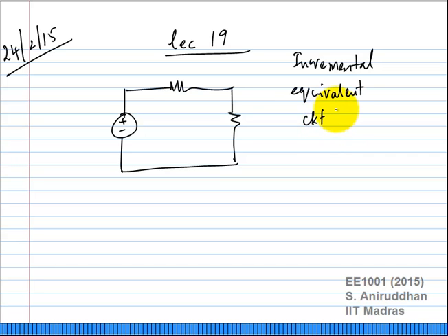What happens to the voltage source? The value of the voltage source is delta Vs. The value of the resistance stays the same, R1. The value of the diode is replaced with a resistance Rd, and Rd is nothing but 1 over f prime of V at V naught. Is that clear? How do you know it's just a resistor, and how do you know the circuit looks exactly like this?